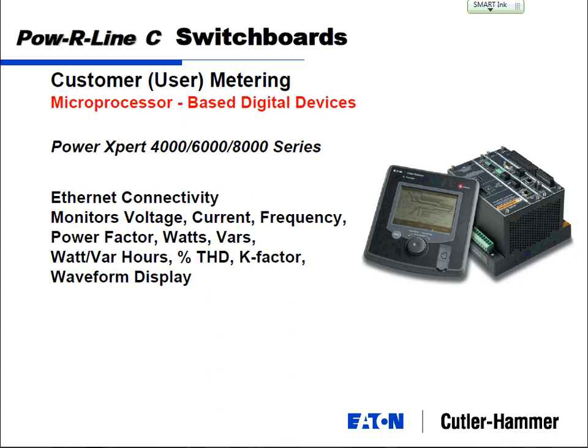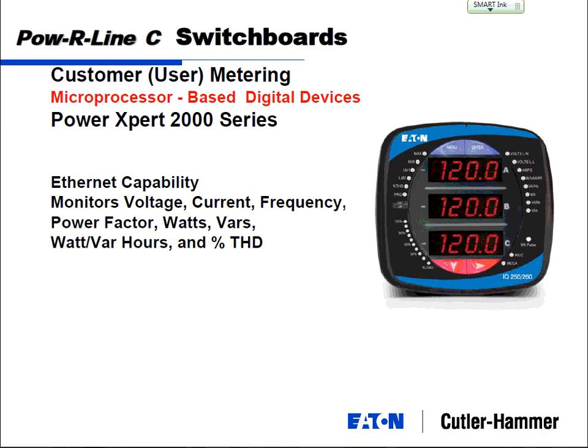And they added this meter. They separated four loads, like wings of the building, so they had four of these meters in the switchboard looking at all four loads, expecting to get 150 to 200 amps, I think, per little section. When they actually got it up and running, they ended up going with LED lights, and they were barely getting anything on the meter. They're showing like 50 amps, 30 amps, on this huge service, and they're going, well, I guess we only needed 1,200 amps to run this building, and instead they got a 3,000.